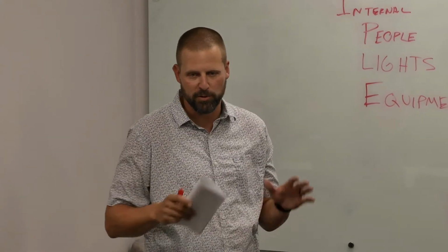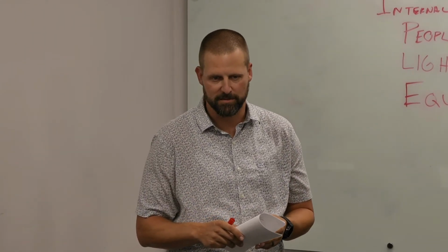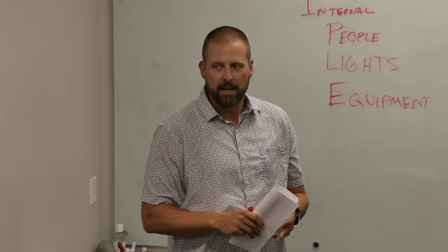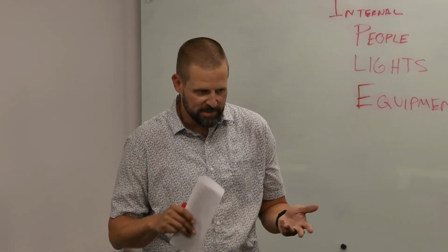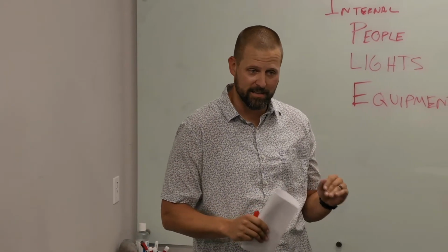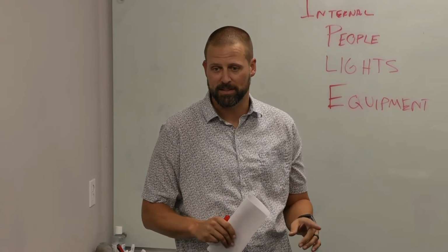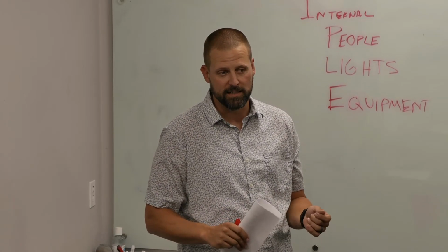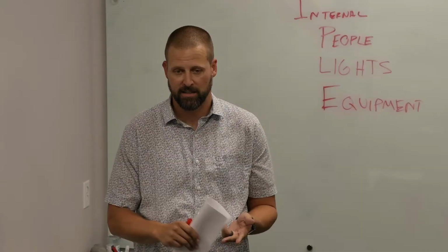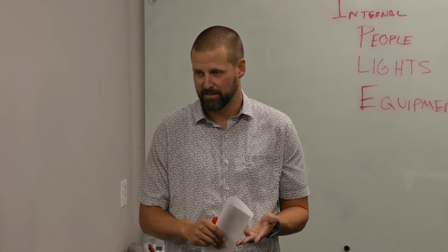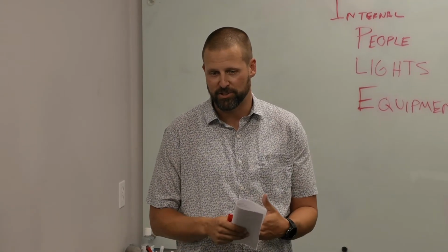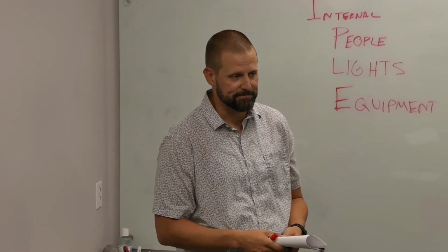And then clean rooms or labs usually have some sort of equipment, and usually things we don't understand. I guess one of the things I'll point out for kitchens, labs, servers, is we can make assumptions, and we've done a lot of these type of things, so we have a general idea for what they need, but usually we're looking for an engineering direction from a lab planner, a kitchen planner, or an IT person to give us those heat loads. That's not something that's intuitive to an HVAC engineer and ranges a lot.